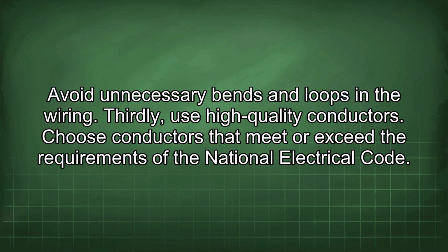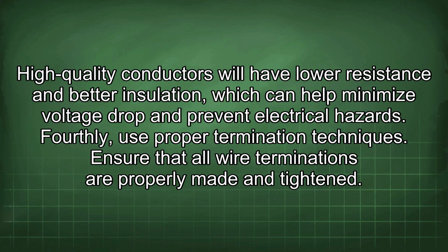Thirdly, use high-quality conductors. Choose conductors that meet or exceed the requirements of the National Electrical Code. High-quality conductors will have lower resistance and better insulation, which can help minimize voltage drop and prevent electrical hazards.